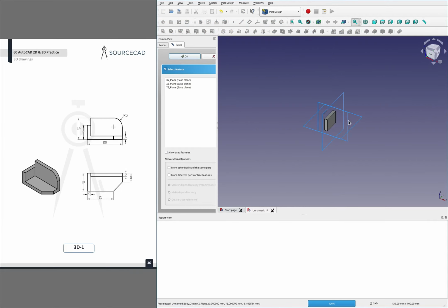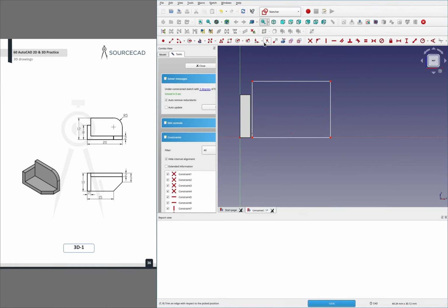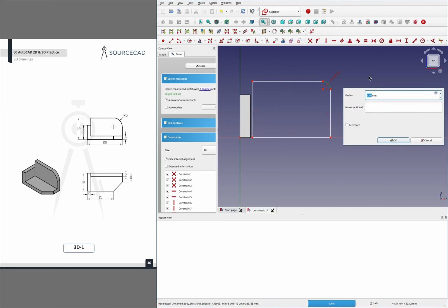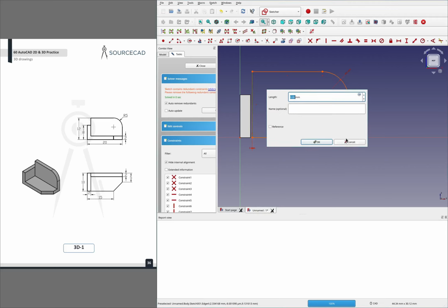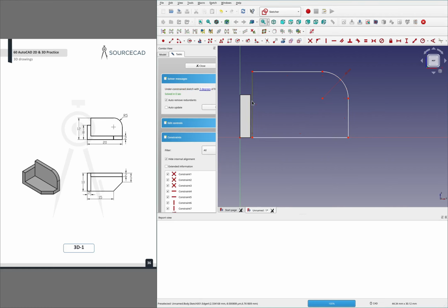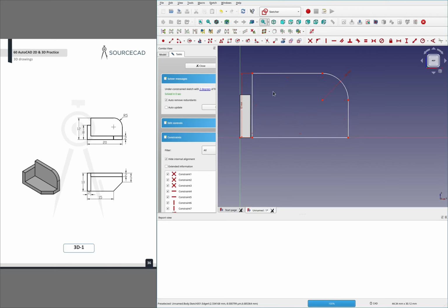Okay. So moving on to the second face. Second face is just a square with a rounded edge here. So I'm going to get myself the square tool again and get us the chamfer tool. Okay, so now that we've got a round, we will radius that at 5 and then dimension the height, except it's Shift V instead of Shift H. Got myself confused here. The H in height, except I dimensioned horizontally.